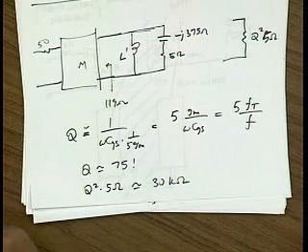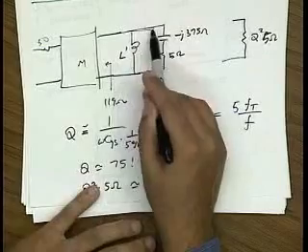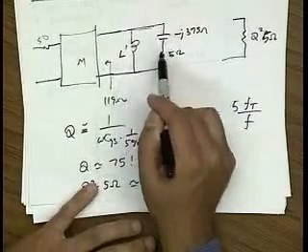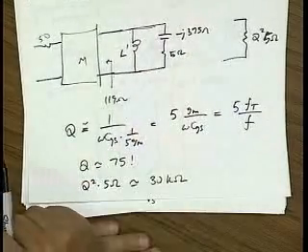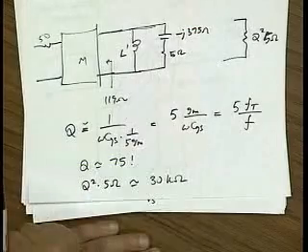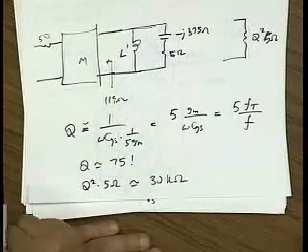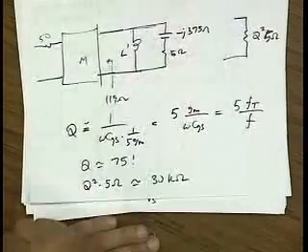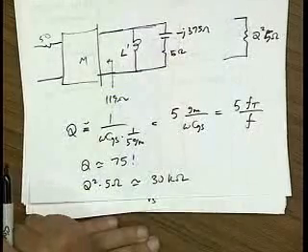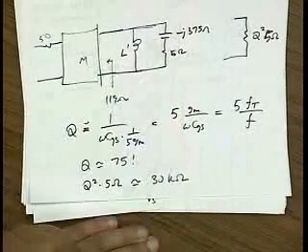Then use option number 2 where I put the inductor in parallel with it. Yeah, so you mean I could put a little inductor in series here, reduce the Q of this network. You can play games, right? And I'm sure, in fact, you're absolutely right. You can make this work. It's not going to be simple, but it's going to involve a couple stages, effectively, of matching.